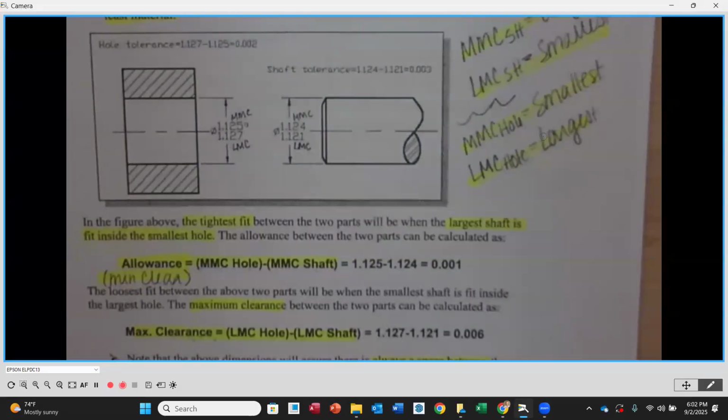Tyler: You have maximum material condition on top, which, from what you all told us, it's better 9 times out of 10 to be at max material condition than least material condition in GD&T. Yeah, we use that a lot. That's a good thought, but I'm sorry, it's not the reason that it's there. It's a manufacturing reason. I know I've said this before, but it just depends. Anybody have a manufacturing reason?